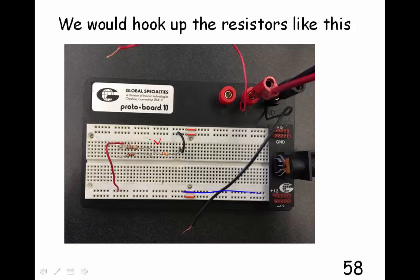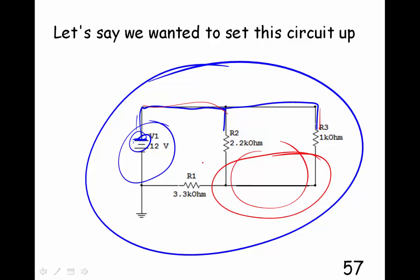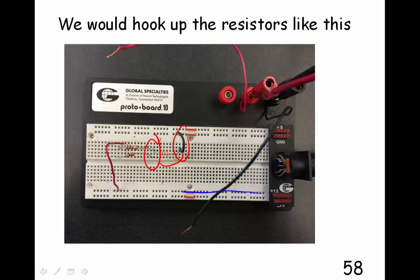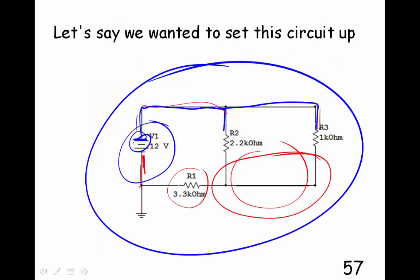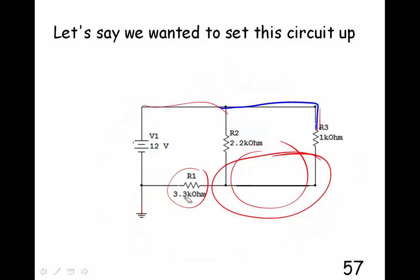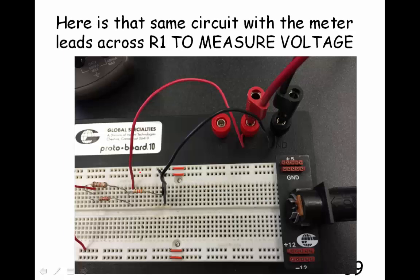And then the other side, there's that junction, and it goes over to ground. And let's see if it does in here. So there's the junction. It goes through R1 into ground. And then the ground, I'll just point out that the ground here is connected to the power supply here, but I keep pushing the wrong button. Sorry about that. Here, this ground, you don't have to connect to the circuit. That's only for the Multisim, because in our circuits, the negative terminal of all of our supplies is hooked to ground, except for the negative side, where it's the positive one that's hooked to ground. So it's already hooked internally to ground.